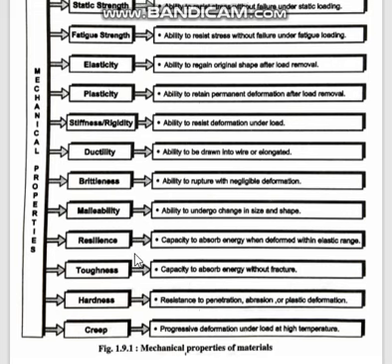Then something called resilience. Resilience means the capacity to absorb energy when deformed within the elastic range, and up to fracture is toughness. The ability to absorb energy up to the elastic point is resilience. Up to the fracture point is toughness.